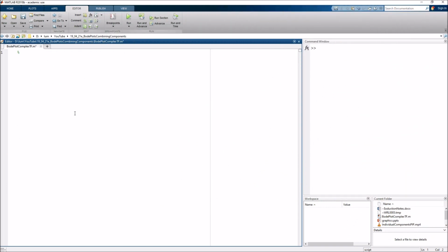All right, so here we are. Let's verify our Bode plots using MATLAB. Let's go clear, clc, close all, and then, if you remember, first define the transfer function. In our case, our g of s. What was our original g of s here? I'm trying to remember. Oh, I think it was 50s plus 5 all over s squared plus 30s, right?